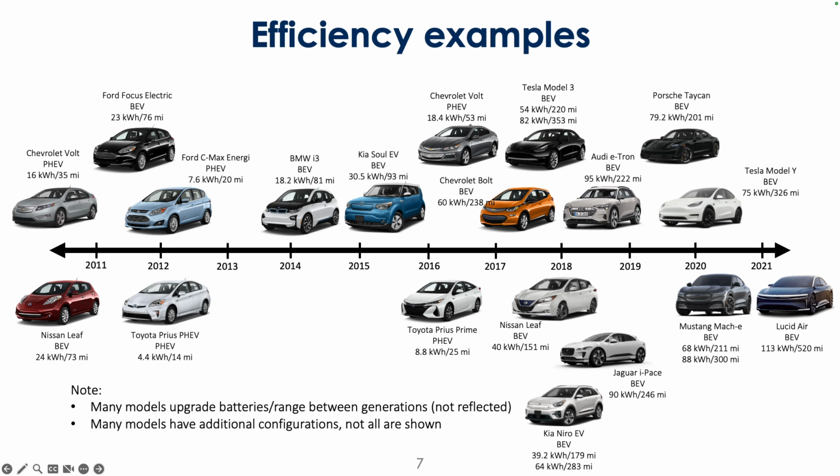So that might be more like a giant Hummer EV, for example. I think that one is even worse. But like a Cybertruck or F-150, those are going to be like 40 to 45 kilowatt hours per 100 miles, whereas something like an Ioniq 6 or like Lucid, I think, are going to be closer to the 0.2 to 0.25 kilowatt hour per mile, 20 to 25 kilowatt hours per 100 miles.